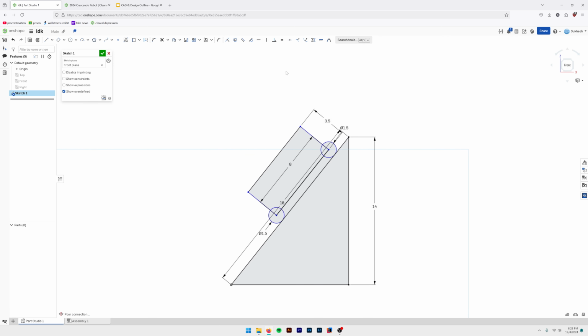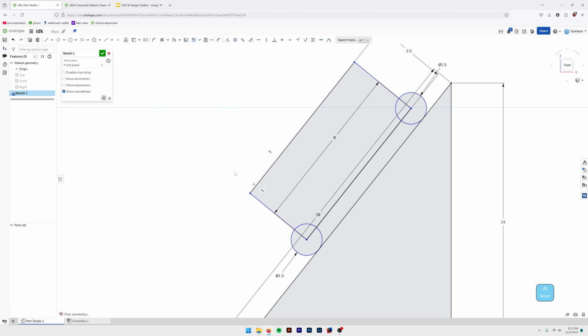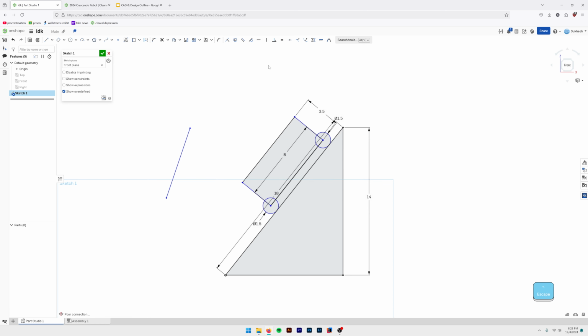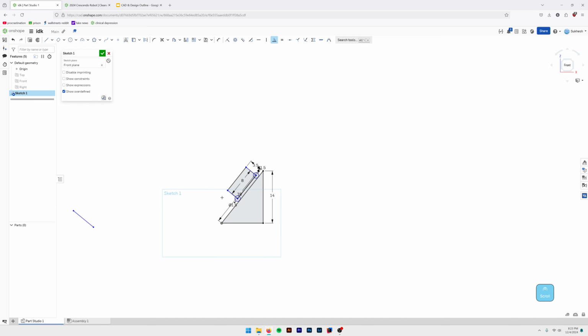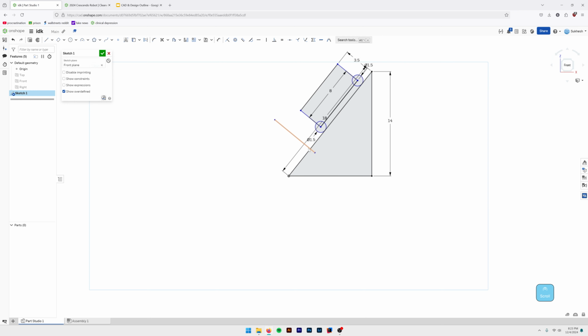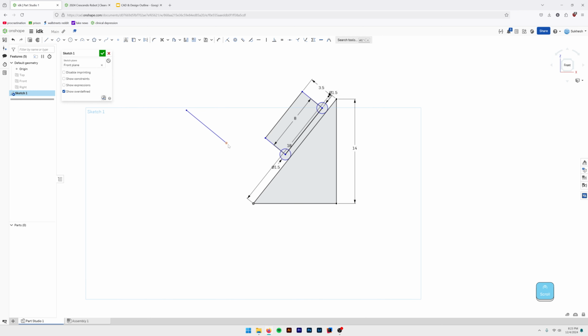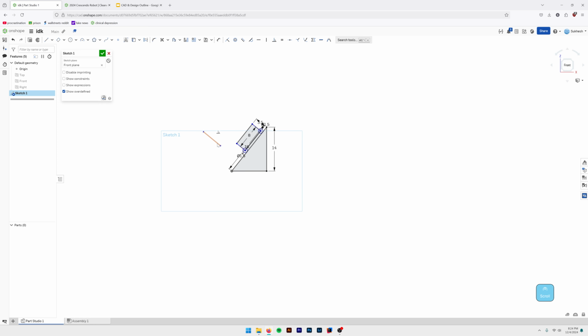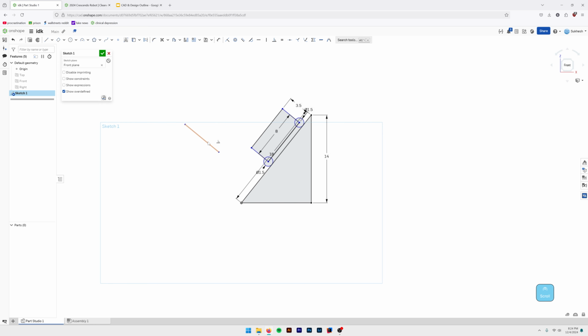You don't really need to worry about the other ones. Perpendicular, that makes sense, right? Any 90-degree angle, you have a line over here. Perpendicular, you can just select the line and that line, and it just flew off somewhere. I'm just gonna bring this over here. Notice how it's perpendicular. Another cool trick is, in case you have a line that looks like this and you just can't tell, if you press X, that's for extend, and if you just click the line, you can just drag it until it meets whatever point that you want it to meet. So if I just click over here, then it just extends the line like that.